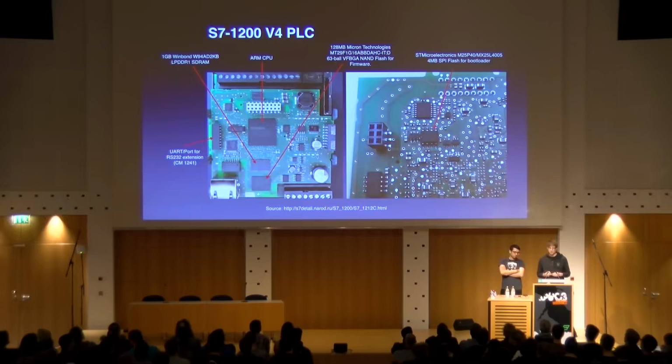So generally, as mentioned, you have the first stage of hardware initialization, and then basically bringing the bootloader to the RAM, and checking the bootloader CRC checksum, to make sure that it's not manipulated, which again can easily be bypassed.